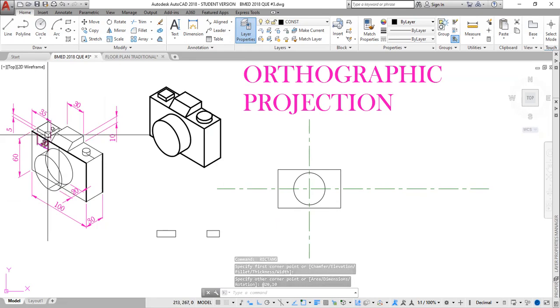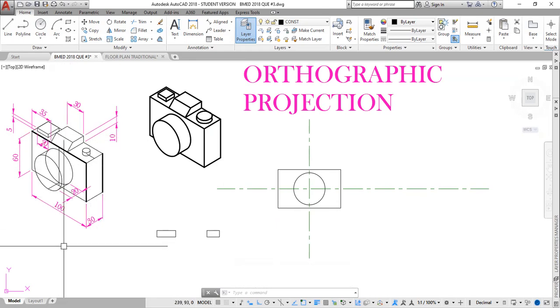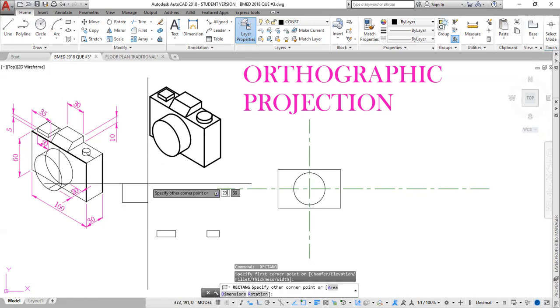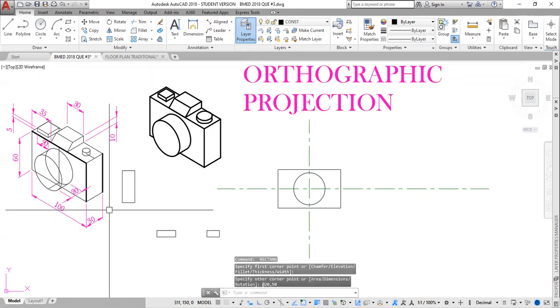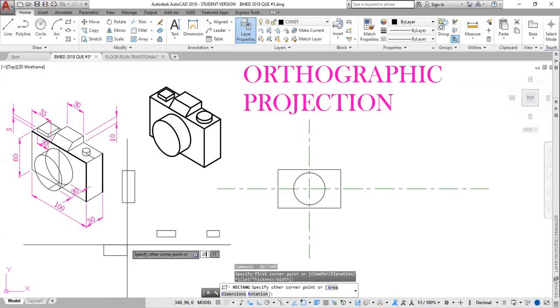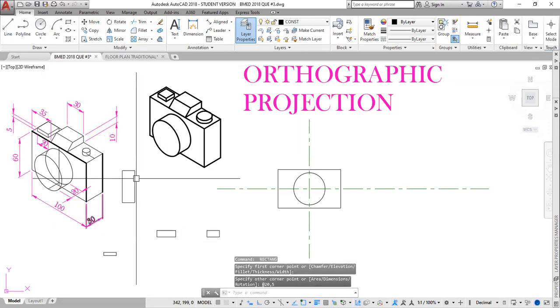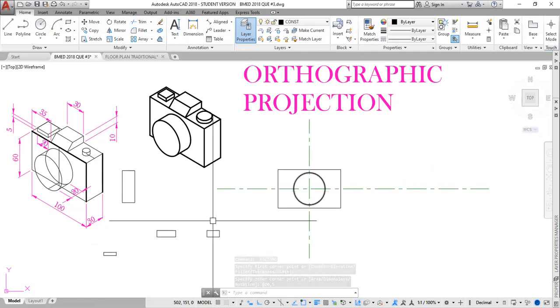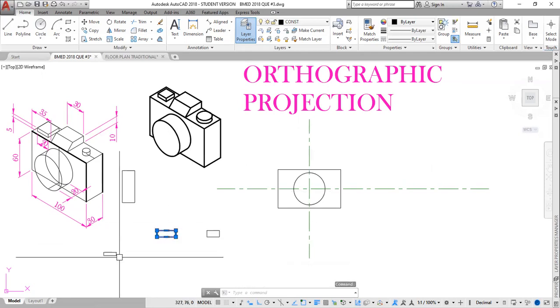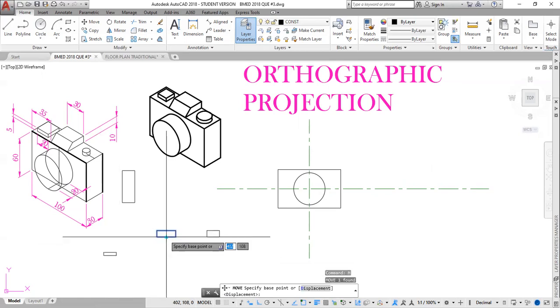Over here, this is 20 by 10, so I hit here, rectangle, 20, comma, no, 5, 20, comma, 5, enter. Oh, space bar. This is 20, comma, 5, enter. All right, yeah, so we have this now. Now, I need to drop in, so this one goes here, M, enter. Select here as my base point. I need to deactivate my orthogonal mode or force it to go right there.